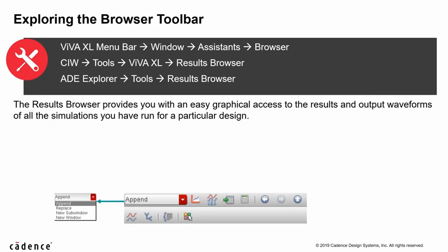Following that, we have two plotting buttons. You can select a signal or signals and click the plot signals button to send them to the waveform display. You can click the plot signal from all DBs button to plot all the waveform signals present in all the open results directories. This helps to compare the signals that are common to all the open results directories.